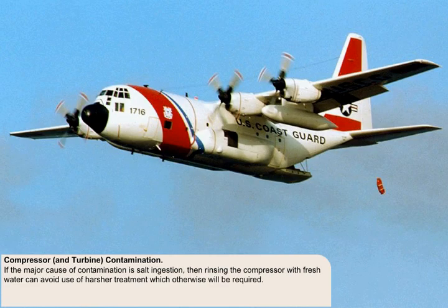If the major cause of contamination is salt ingestion, as might be the case with an aircraft which flies for long periods low over the sea, like this US Coast Guard C-130, then a timely rinsing of the compressor with fresh water can avoid use of harsher treatment which otherwise would be required.